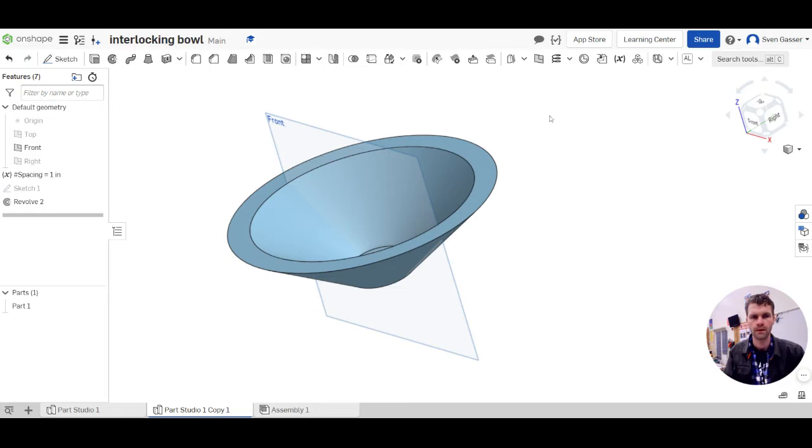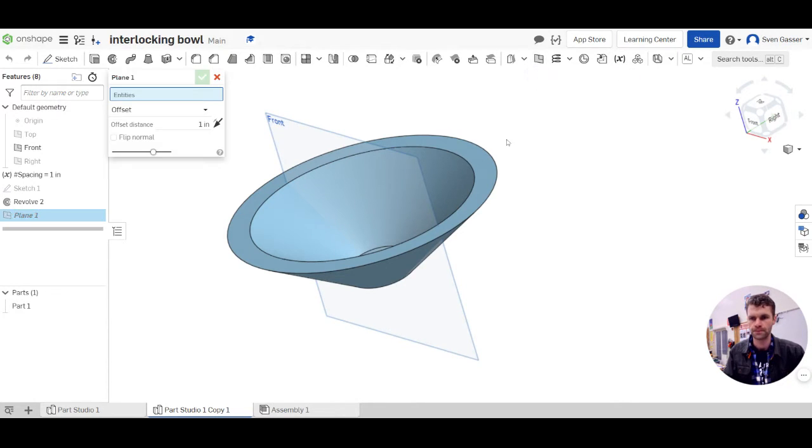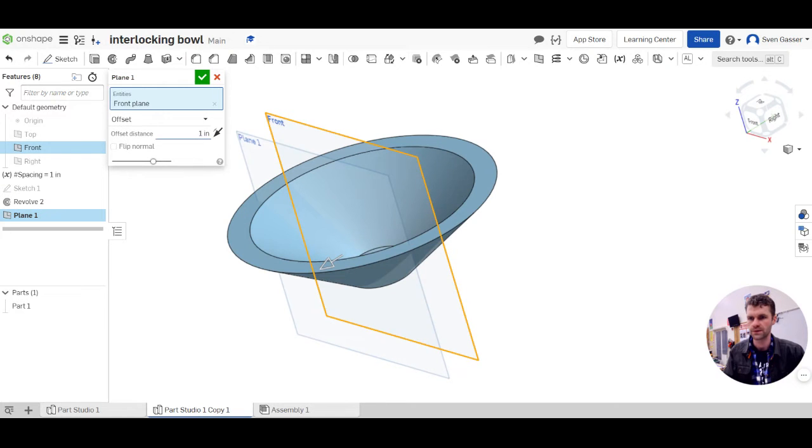So we are going to say new plane, click on this surface, and then instead of typing in a number here, we're going to use that variable we have, so that if we decide, actually I want those gaps to be a little bit bigger between the ribs or smaller, we can really easily change that later. And I'll show you what that looks like later.